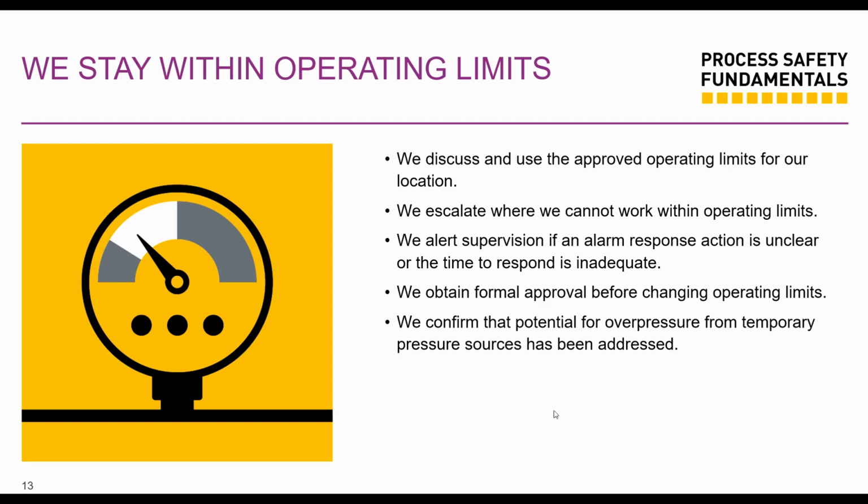Then the fourth is stay within your operating limits. This is so important. So many times operators ignore it: you see this pressure spike, this temperature spike or temperature dip, and you just ignore it.